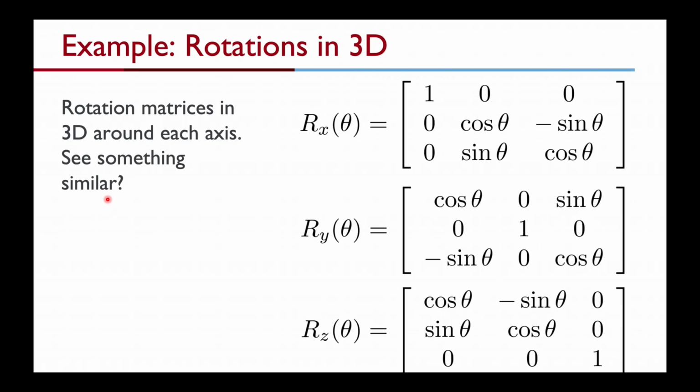So in fact, if you see this slide and then go back in this video, you will find that the 2D rotation matrix we saw was exactly this component which describes the rotation along the z-axis in a general 3D environment. In fact, remember how we even emphasized that the first column is the x plus the y component of the new unit vector for the second frame, and then the z component was irrelevant when you rotate around the z-axis.